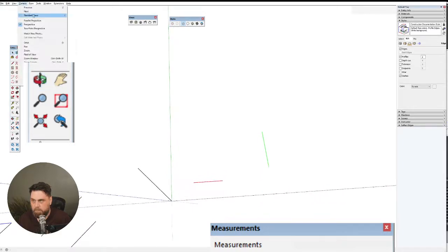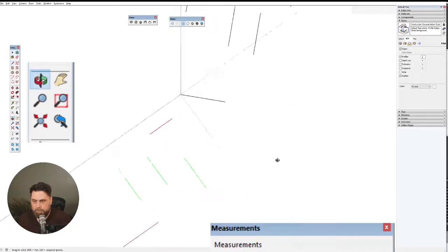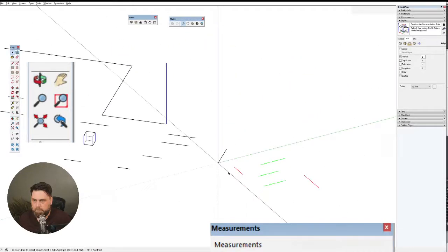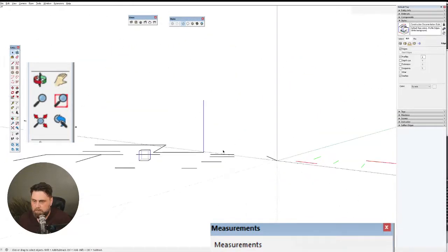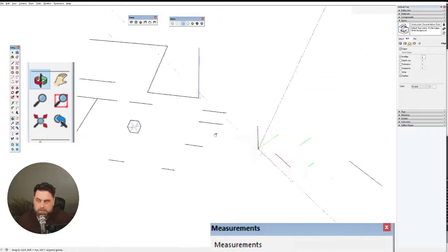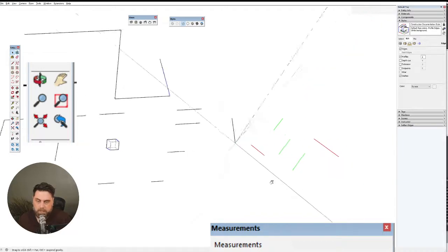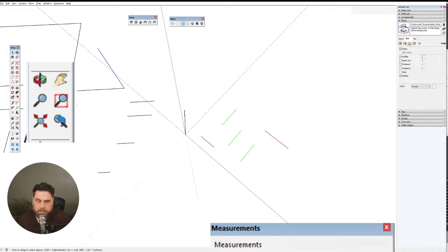And again, if we went to parallel projection, you can see that these are indeed square. But if we look at those in comparison to what we've already drawn, you notice how these have all gone back to black because we are set up here to mark by the axis. So now these all appear to be off axis, even though they were set to our original axis that we had. But now these are on axis, so they're turning the color indicators.